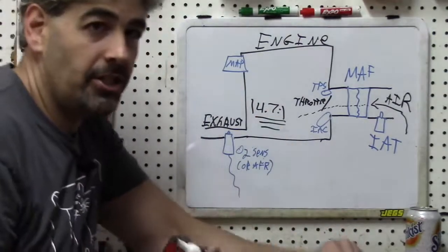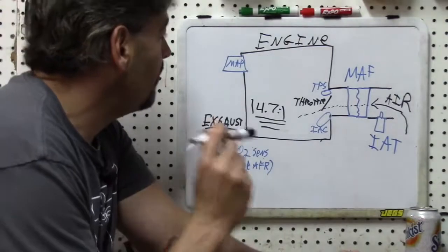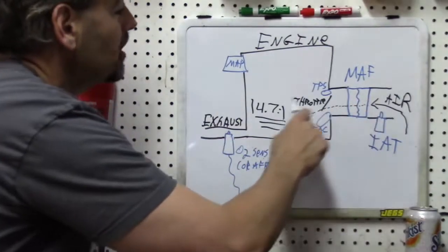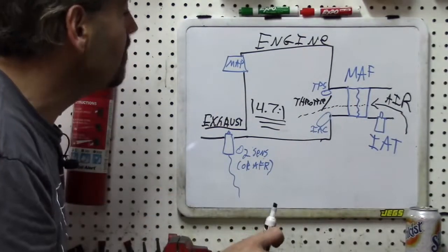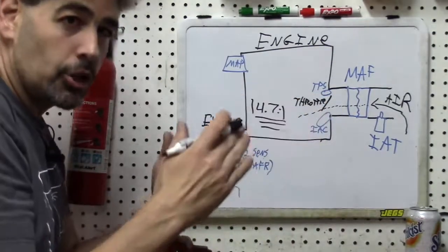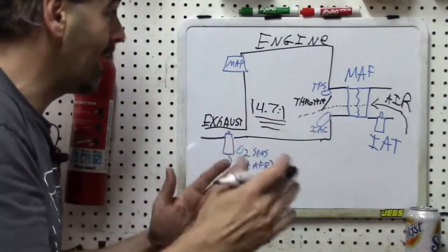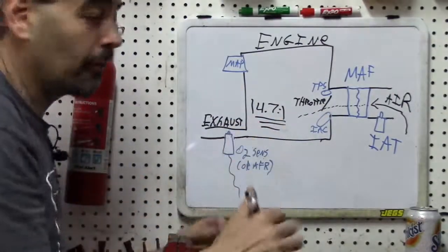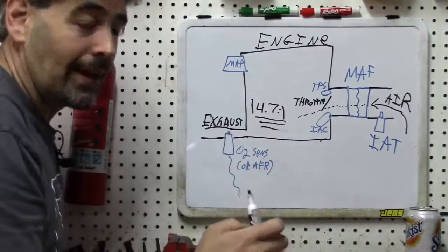In order for an engine to do this, it is essential that it knows how much air is coming to the engine, and then it adjusts the fuel delivery by lengthening or shortening the injector pulse length to match the fuel delivery that would result in that final ratio.